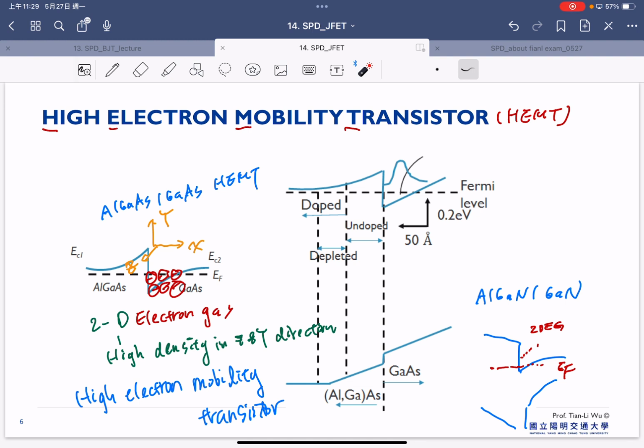So this is exactly similar to the degenerate case, because right now our Fermi energy is above our conduction band. So that's a place where your semiconductor is not like a semiconductor anymore. It's like a metal. The conductivity is very high, because we have very strong electron density here.